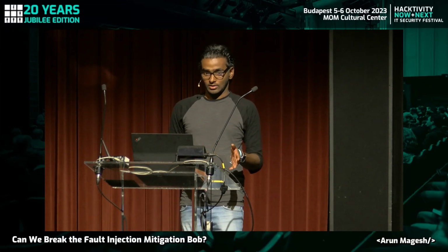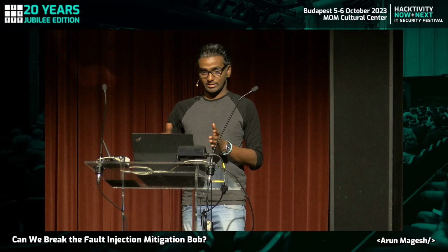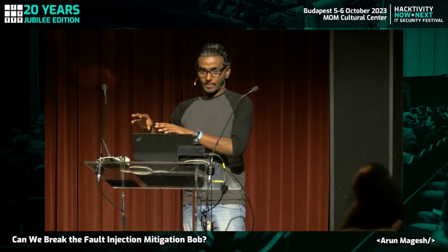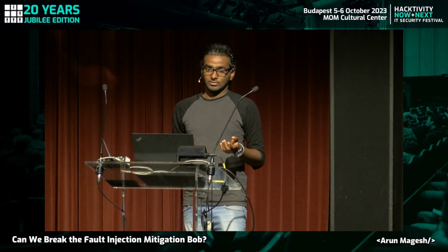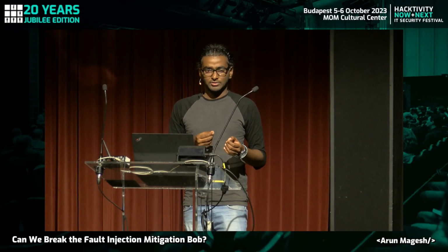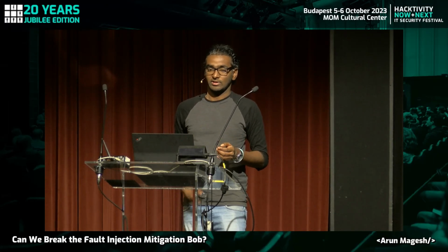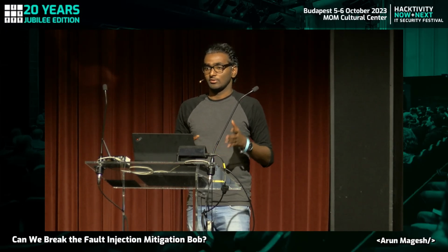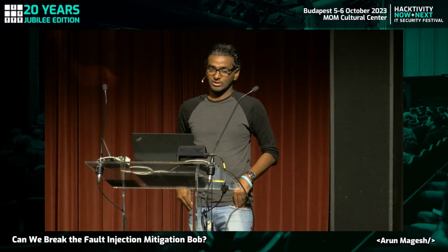You don't have to. You can also synchronize your clock. If you want a very precise glitch, if you glitch only a specific instruction, then you can synchronize this. For example, the ChipWhisperer tool has an ability to supply the clock to your target, and also at what clock you want to glitch. So you can also do that, but you don't need to really do that. Usually, not all chips are the same. Because of the way your chips are fabricated, your instruction will actually have some sort of jitter. So you don't necessarily need to have a synchronized one. You can just randomly glitch based upon, let's say, a specific trigger, which you already know. It's just a matter of if you have precise timing, it's easier to glitch. But even if you don't have it, it will take a bit more time, but you can still glitch it. It shouldn't be a big problem.